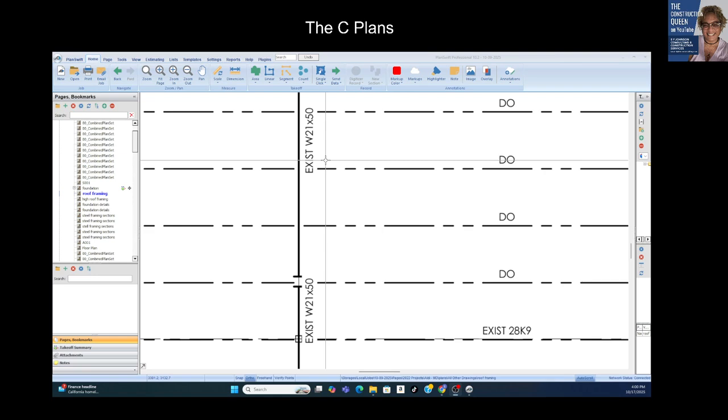Which ones to use depends on the structural engineer. But when you are estimating fabricated metals, anytime you see that, those are priced by the pound, not by the square foot or by the linear foot. And so you have to be able to convert that beam to a weight.